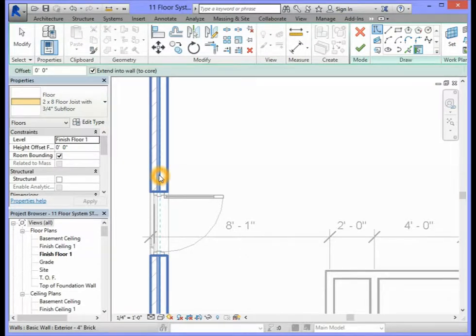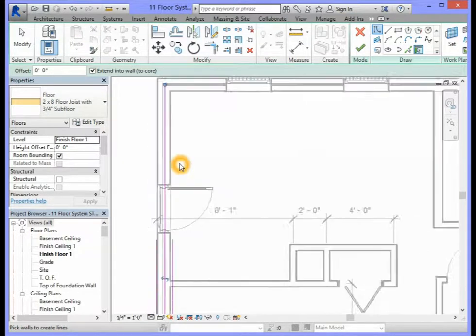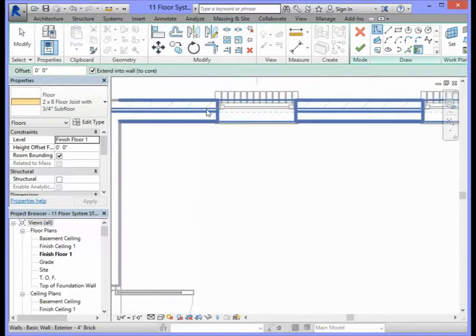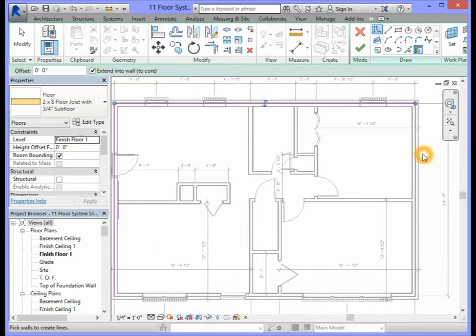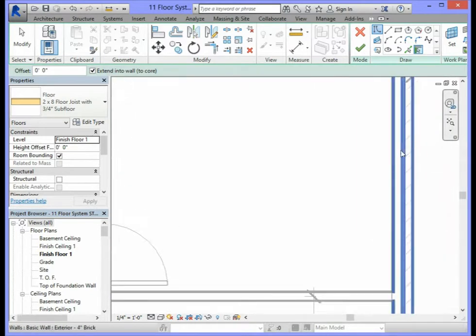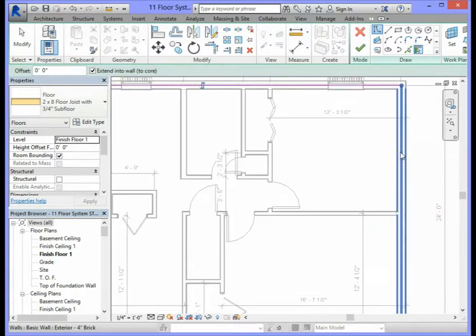So you will select this wall, and again, when you select the horizontal wall here, make sure that the green dotted line is lined up with the exterior face of the stud for the exterior wall. So you'll click there, and what you should see is a magenta line appear where you're clicking.